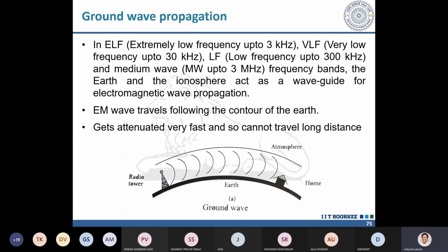Then in submarines, where communication happens in a very nearby range under the sea, you don't have a skywave or satellite, so there you use the ground wave, and it propagates over the bottom layer of the sea. But again, it cannot communicate over very far distances. The ground wave dies out, so it can be used only there.